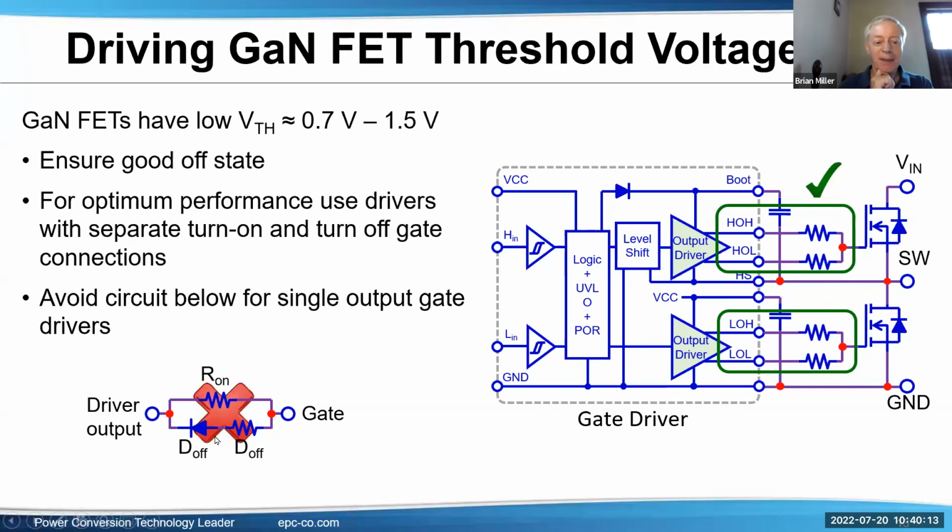So it's not just the voltage, but also unintended parasitics that aren't really specified that can cause some odd operation, and we've seen it. You're certainly welcome to try it, but in our experience it is better to use just a single resistor, to avoid the possibility of something happening due to greater complexity.